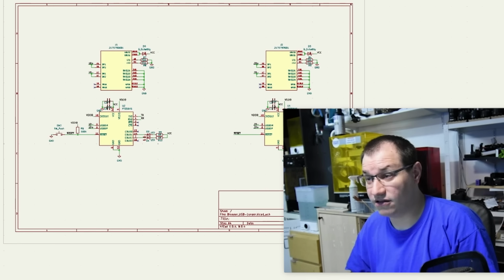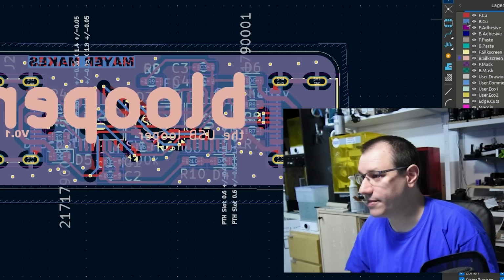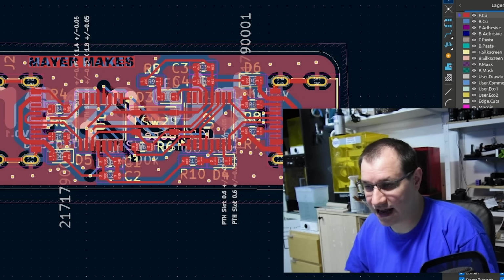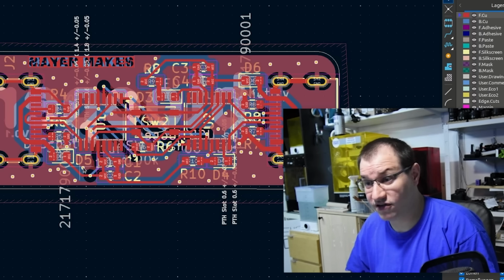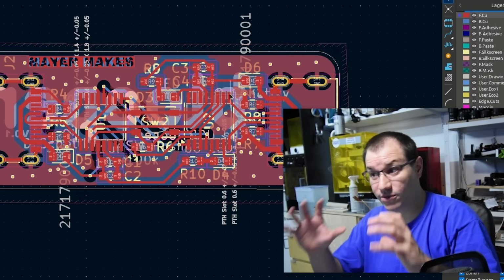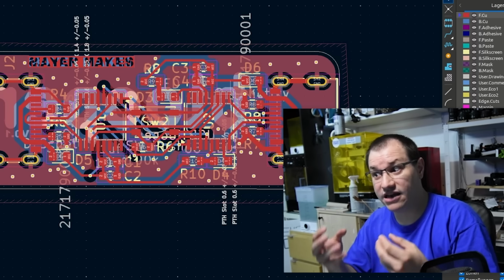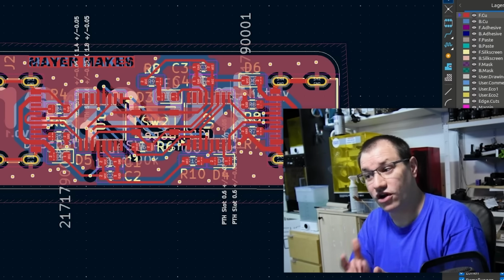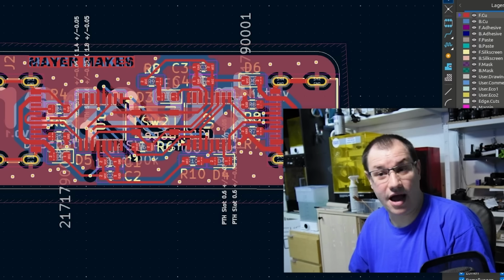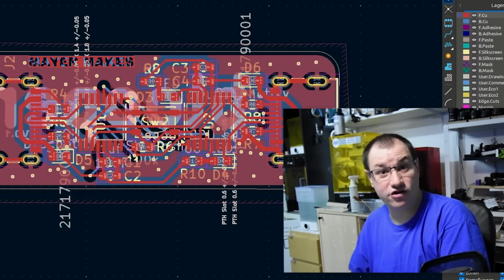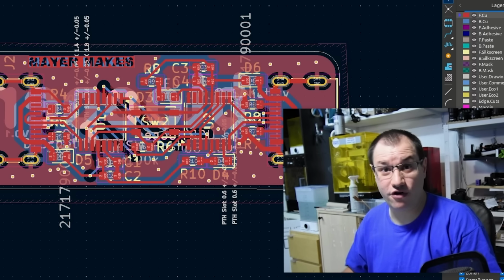If you look at the board design, you can see Blooper on the back. And if you look at the layers, it's not that complicated of a layout. But do you see these points here? That's via stitching. That's important so we don't have any crosstalk on here. We need to have very good, very solid ground planes. Yeah, that's how I made this thing, and you can too, because you can download all the files for free on the element14 community.